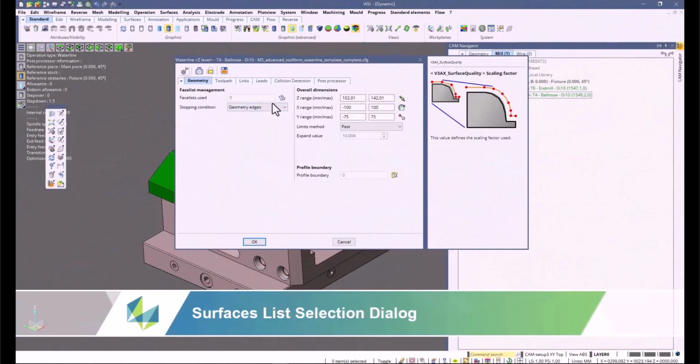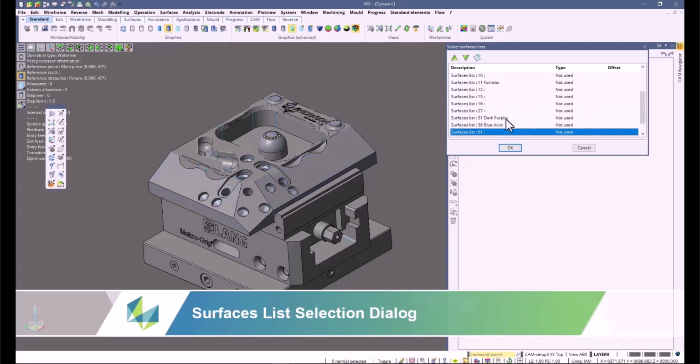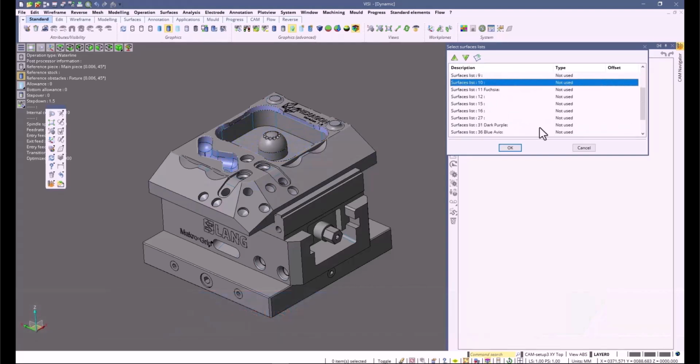So here's just a quick video kind of showing the surface list. So you can see here's your surface list, here's all the different selection areas, the variables, you see highlighted which one is actually being selected right now, and you can go into these areas and simply double click on them. Double click will toggle through those different options. You can also right click and see a list of the different surface areas as well.